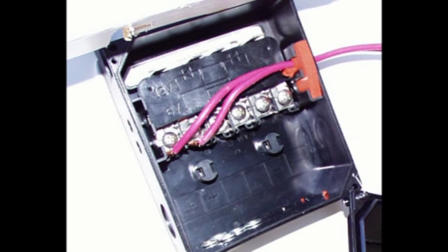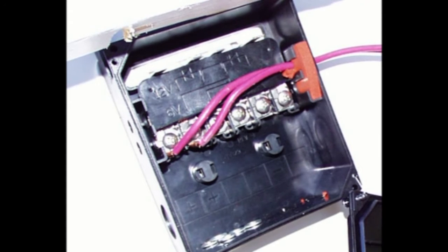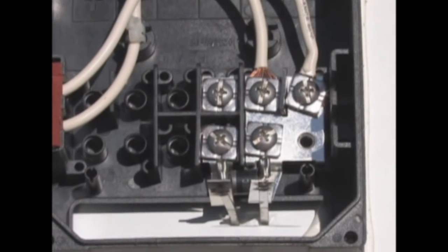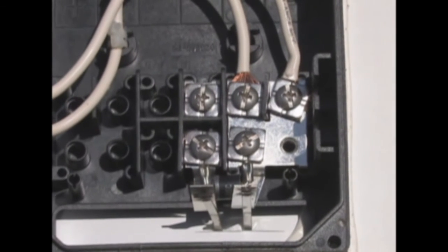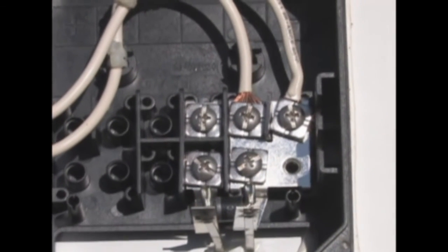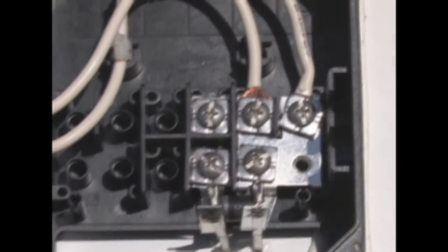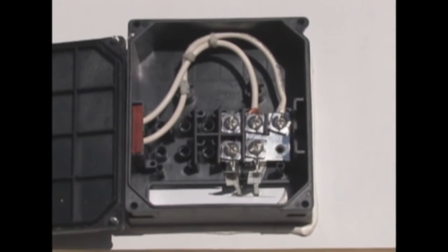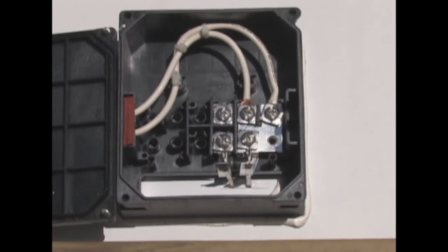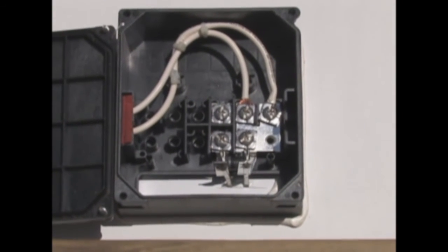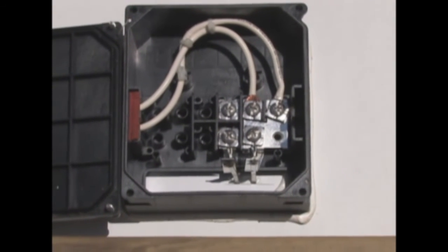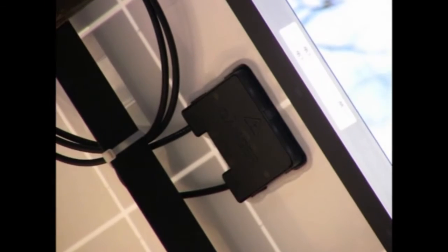Smaller panels may still come with a connection box like this. Here's a close-up of the wire connections. Notice that you just strip the end of the wire, loosen the screw head, and place it under the cap, and then tighten down. Don't over-tighten, just tighten enough to hold the wire in there. I'm using 2 wires in this situation just to double up on the copper and be sure I have very low loss between each of the panels.